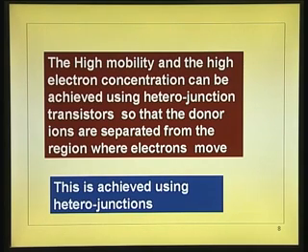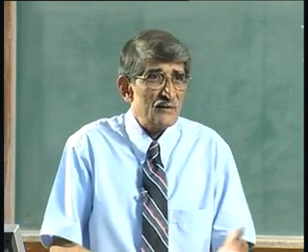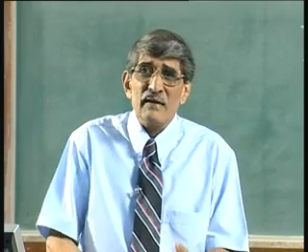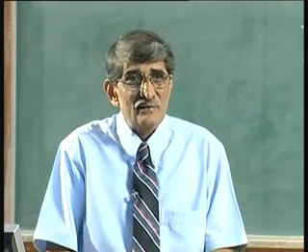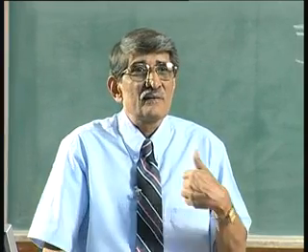Now, you can see we are moving from the MESFET. At this point we will stop discussing the MESFET structure that we have been discussing, and move on to a device called the high electron mobility transistor, because here doping affects the mobility, since you want high doping. What you require ultimately is high carrier concentration. For a given current flow, the field will be smaller if the carrier concentration is made high.